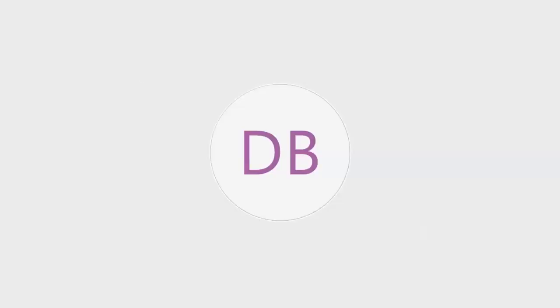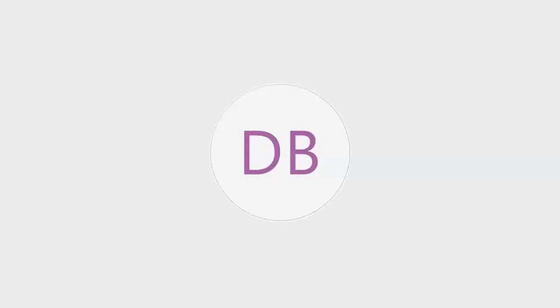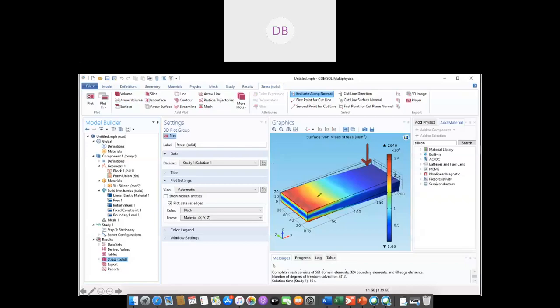So if we want to use a direct measurement, we can use a piezo-resistive cantilever, where this bending will generate a stress in the cantilever. You can see the change in colors. This is the stress introduced into the cantilever. This stress in turn will be converted into resistance. That is the piezo-resistive property, and that is the transduction process we were talking about in the early slides. So in this way, we will be able to measure the mass, the amount of mass that is deposited onto this, right?